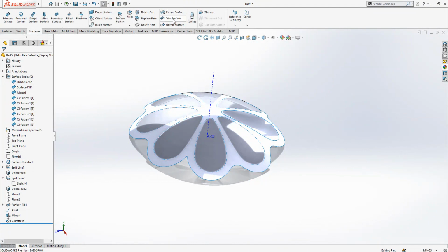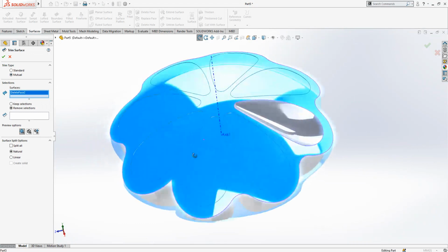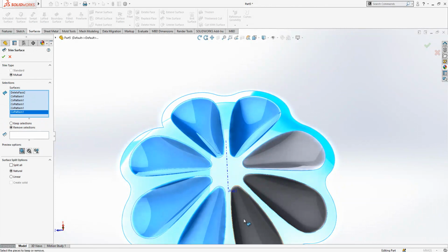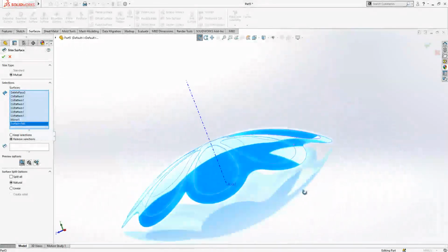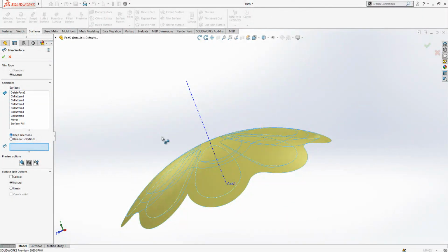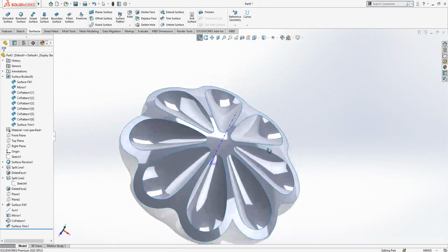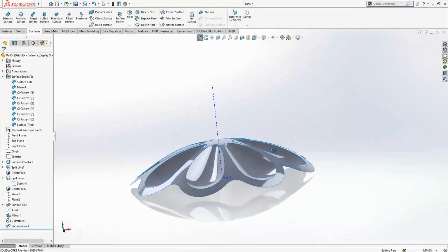We go to Surfaces, Trim Surface. Mutual should be active, and one is this, and then the other ones, except the first one that we delete surface, will be selected. Keep selection will be this, and then unnecessary surfaces over there will be removed.